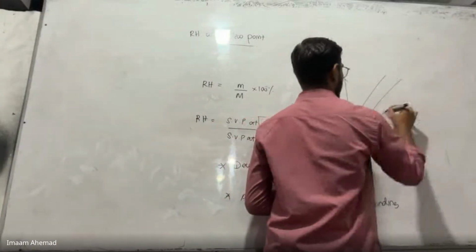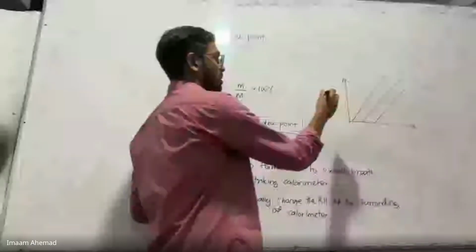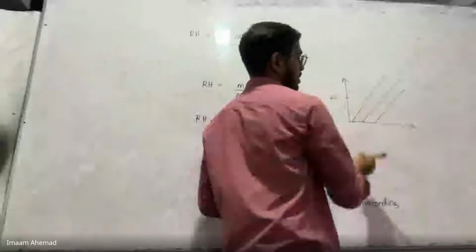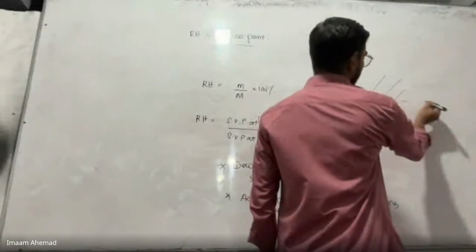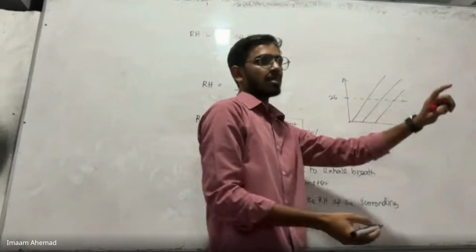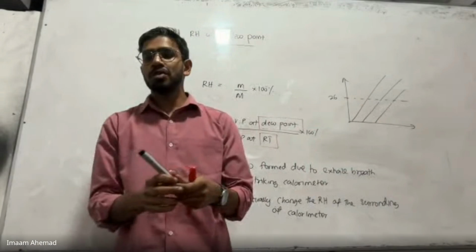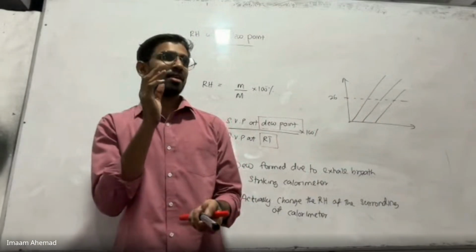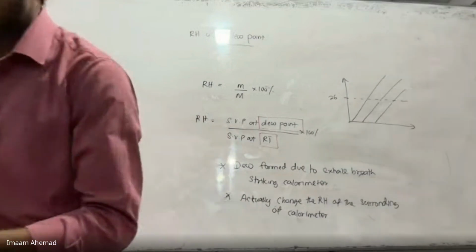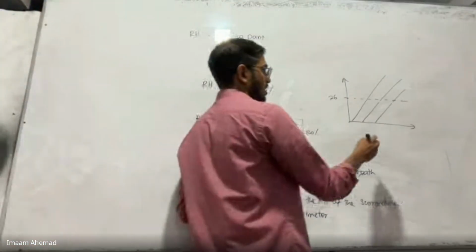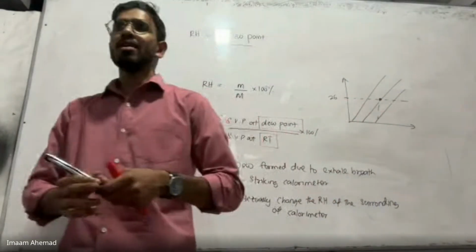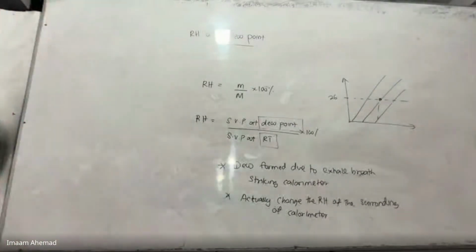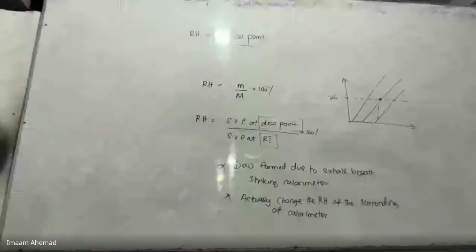So on the dew point side, check the dew point temperature. When you move along this line, it is going to cross these graphs. Check the graph which crosses the room temperature. Room temperature is 30, and dew point is 26. So it's crossing which graph?